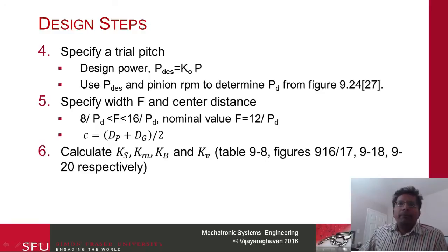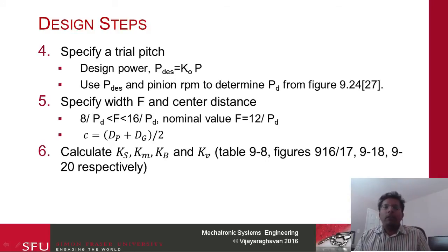Coming back, so we did this. Next, once we have the diametral pitch and we've already designed the number of teeth, we can calculate the center distance and the face width. Typically we choose the face width as 12 over PD, which is the nominal face width.